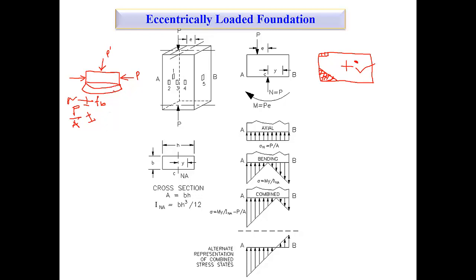So how can you find FB? In solid mechanics we have studied that to calculate the flexural stress of a structure, we consider FB equals My by I. Do you remember this one?